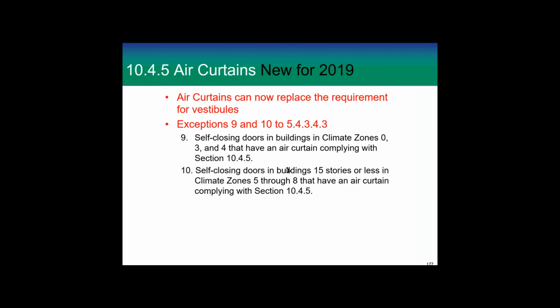So we disallowed those in the colder climates. Now, this is not an air curtain on an open door. It's not like we hold the doors open and we blow the air curtain, and it's the air curtain that's replacing the door. The air curtain is with the door. So if the self-closing door opened, the air curtain would automatically come on, and then it could turn off after the door is closed.